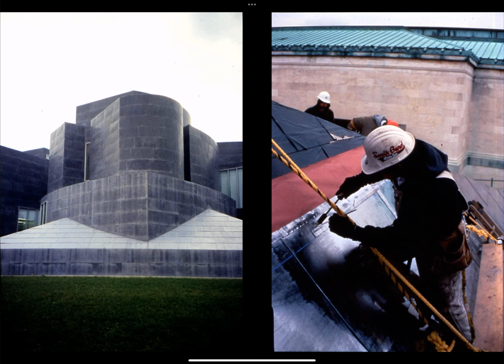It's very thin metal and it has zero spanning capacity. It requires a continuously supporting underlayer. So in this particular case, the plywood sheathing is supporting the metal cladding. The joints with a flat sheet metal system would typically be interlocking joints.